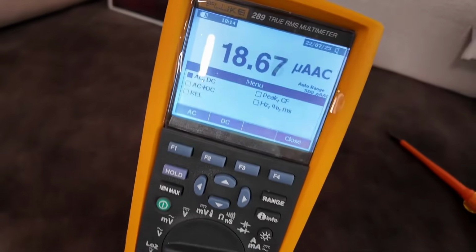Most people ask whether you can use the current from this phantom. Look, 18.7 to 18.6 microamperes. Specifically, I have 30 volts, 18.6 millionths of an ampere. No guys, you can't use this current. And it's more harmful than useful. Remember, people often write in the comments asking why LED lamps glow dimly. So this little phantom can ignite faulty drivers, meaning it can charge capacitors and make LED lamps glow.